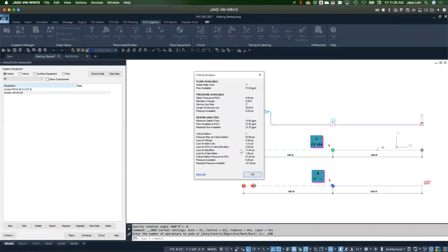So when you're running a low pressure available system and you're trying to stay with low pressures, there are going to be limitations, some things that you just simply can't change. Which means that if you're exceeding because of some of the equipment, and granted, this is pretty standard, anywhere from 6 to 12 pounds of loss is pretty common. Sometimes 4 you can get away with, but depending on the flows that are going through it and the size that you put in, you're just locked into what it is.